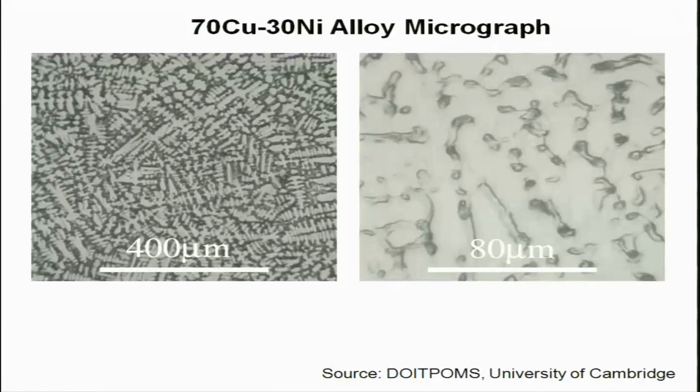If you magnify this image, for instance, you see these dark and white regions, and dark and white regions are nothing but a manifestation of compositional fluctuations in the alloy. But this is basically a single phase alloy alpha with compositional fluctuations. So this is what you are likely to see in a single phase alloy under an optical microscope in reality.